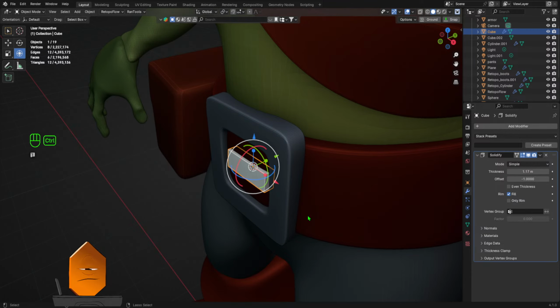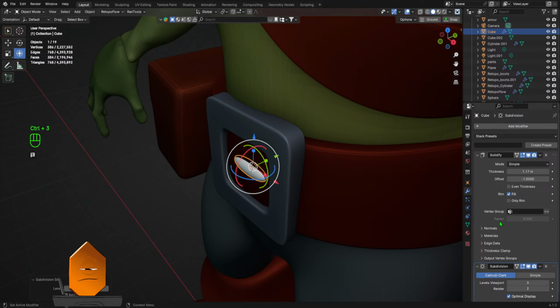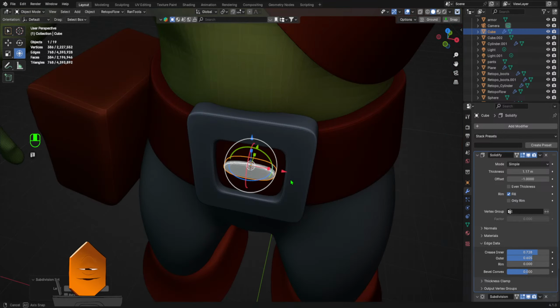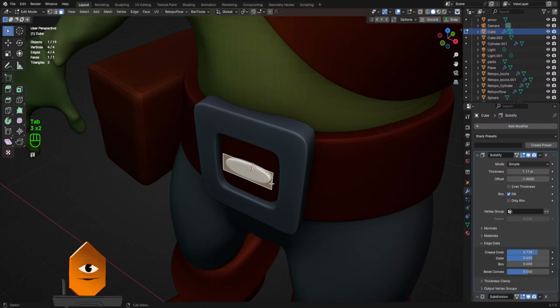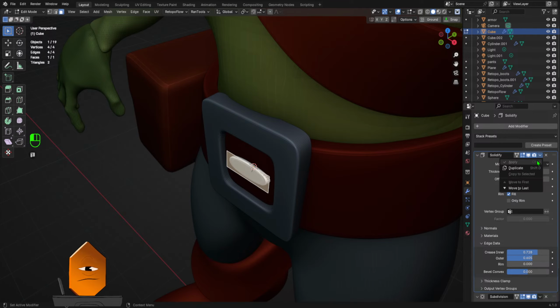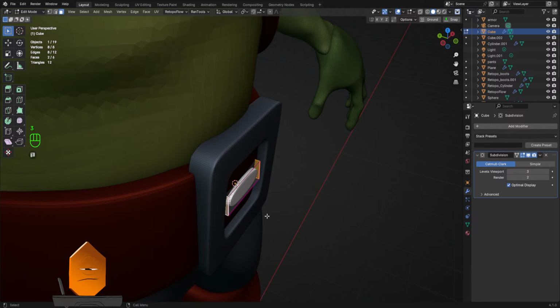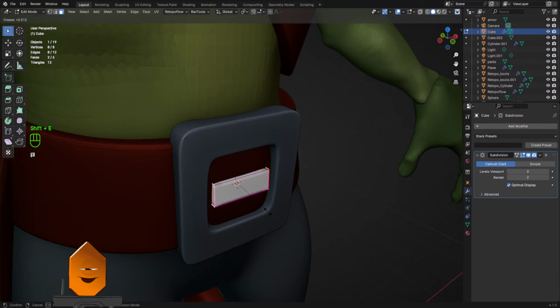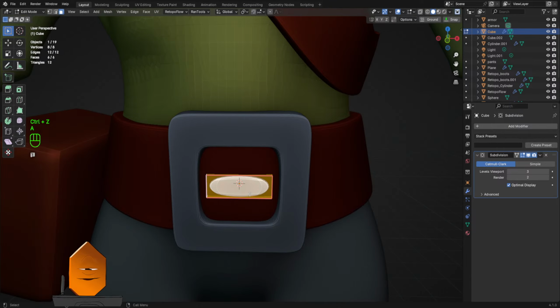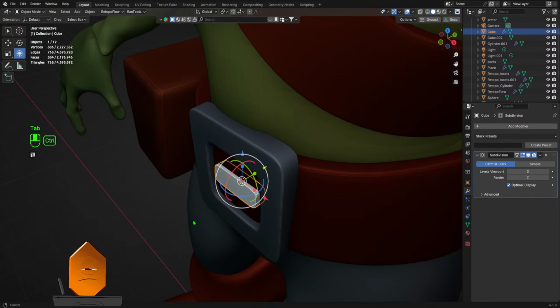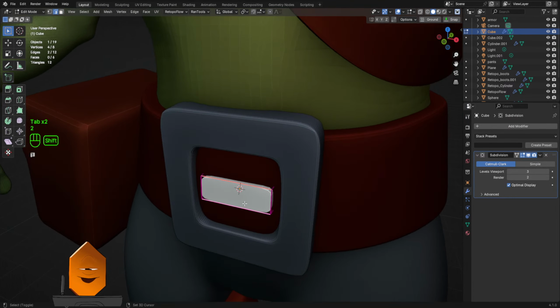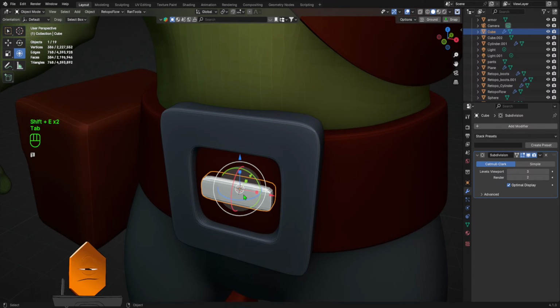But yay. Control 3. Go here, edge data. This just lets me get a very particular kind of shape. And then I can apply the solidify. Then I can sharpen the edges here. Shift E rather. Just do this for all. Shift E. There we go. Actually, I'll drop the sharpness on these, so Shift E and then drag the other way. There we go.